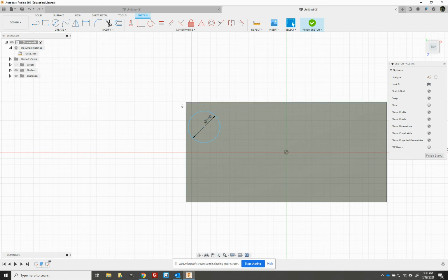All right, now this needs to be positioned from the center point. It needs to be 3.9 millimeters from the left edge and it needs to be 3.9 millimeters from the top edge. I'm going to take my sketch dimension tool, click on it, click on the center point of my circle, click on the top edge. I'm going to drag it out, and of all the dumb luck, it's already 3.9 millimeters. So I'm going to go 3.9, just type it in, and I have that position 3.9 millimeters from the top. I've done this too many times. I put it right where it belonged.